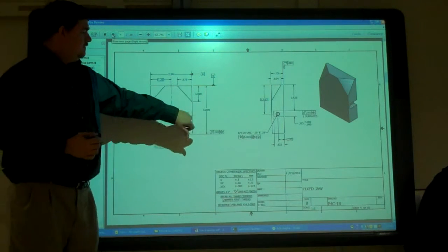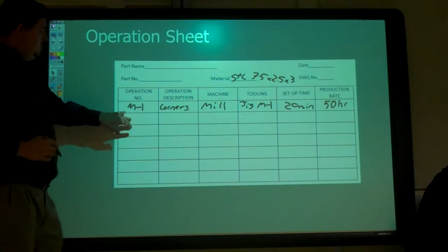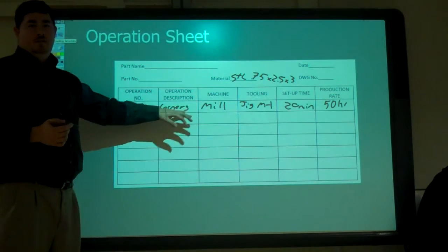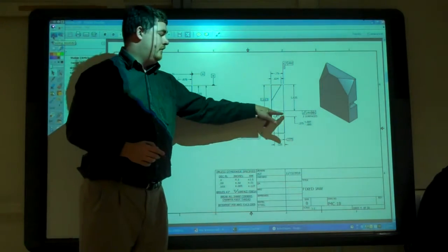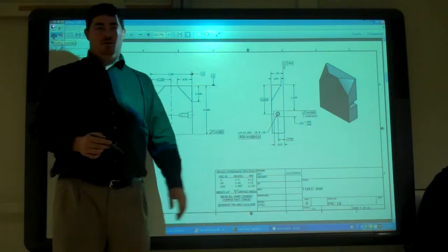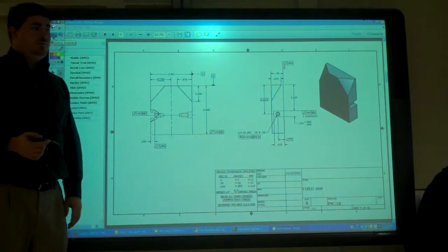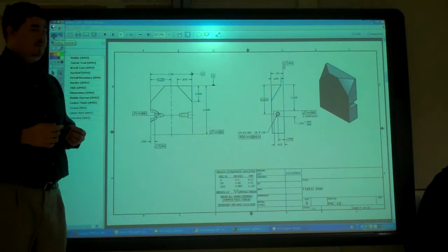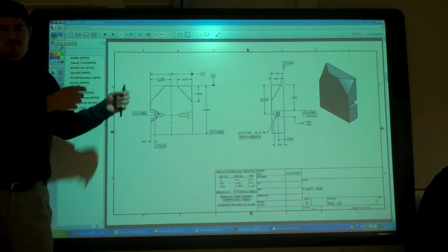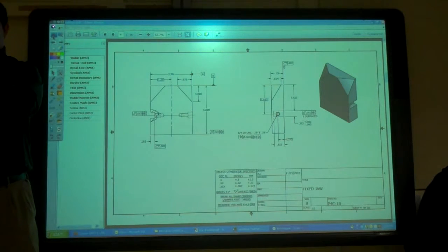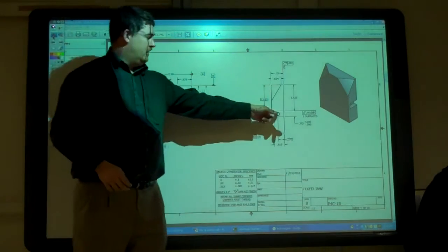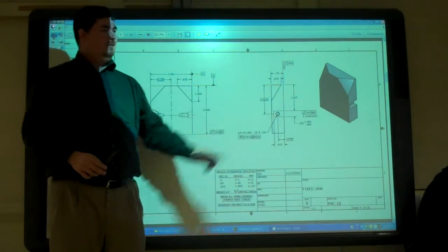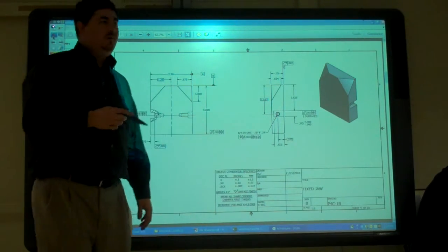So we do the next, go back to our operation chart, put in that, and then you probably have it cut that, drill and tap on the mill, just in one operation. Or you can take it over, drill press it, but probably easier just to have it cut it, drill it, tap it, all while it's in the machine, right?